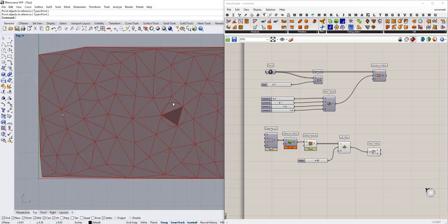Now, if you were to cut these 2 mesh faces the opposite way, instead of connecting from here to here, if you connect it from here to here, then these 3 points would create a circle that's much larger and would include multiple other vertices. So that's why it's a useful sort of algorithm, because it makes as close to regular triangles as possible. Instead of stretching them out, it minimizes the interior angles of that triangle.